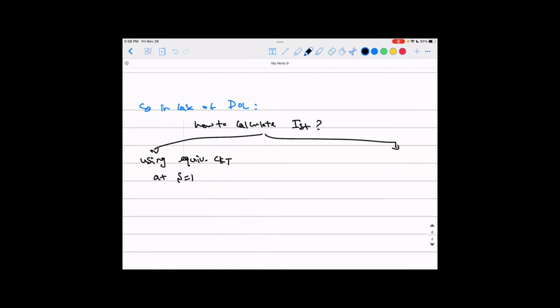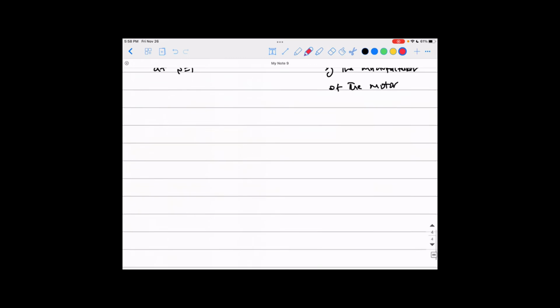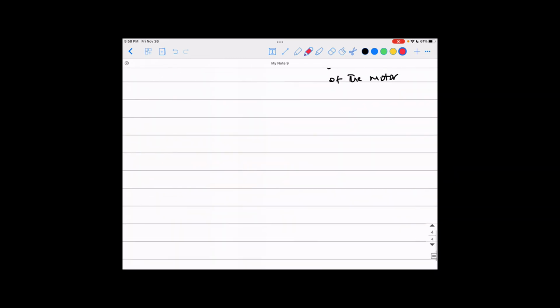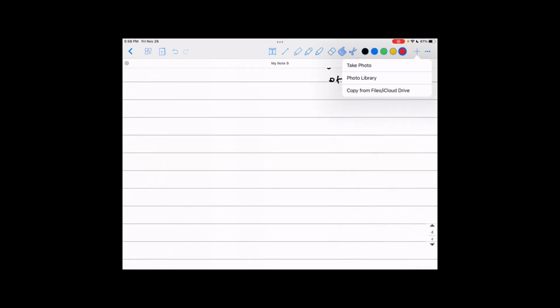So that's why the manufacturer has given us another thing, which is using the starting code given by the manufacturer of the motor. What is this starting code? That code you can find on the nameplate of the motor, okay? And you can use it with a well-known table to find out how much current this motor will draw at the starting, okay?